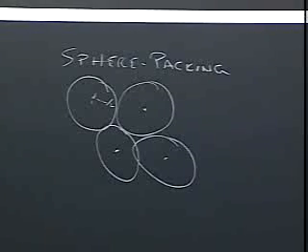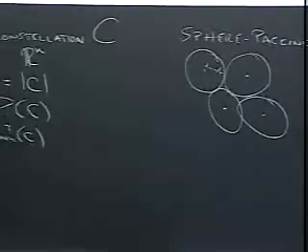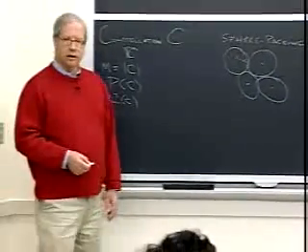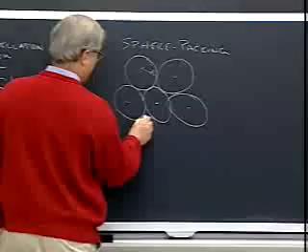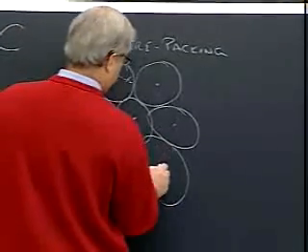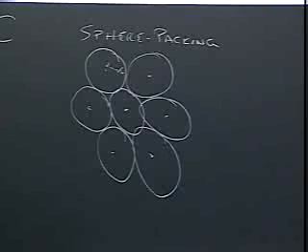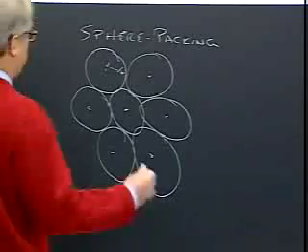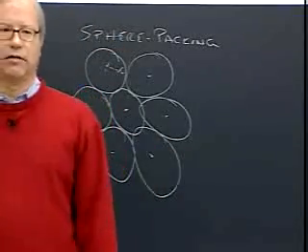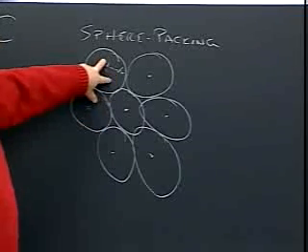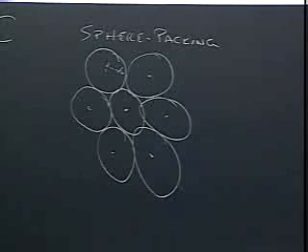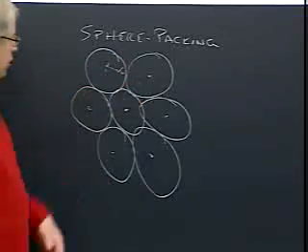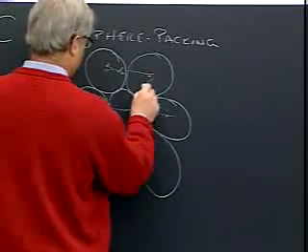In general now, we're going to be thinking of m becoming very large. We want to go to arbitrarily large number of bits per second per hertz. So think of schemes that will continue to work as we add more and more points. And if I do that in 2 dimensions, we'll get penny packing. Take a bunch of pennies out of your pocket and try to squeeze them together as tightly as you can. It's effectively what we're trying to do. They maintain their fixed radius, and you'll get something that quickly starts to look like what is called a hexagonal sphere packing, because the centers line up on a hexagonal grid.